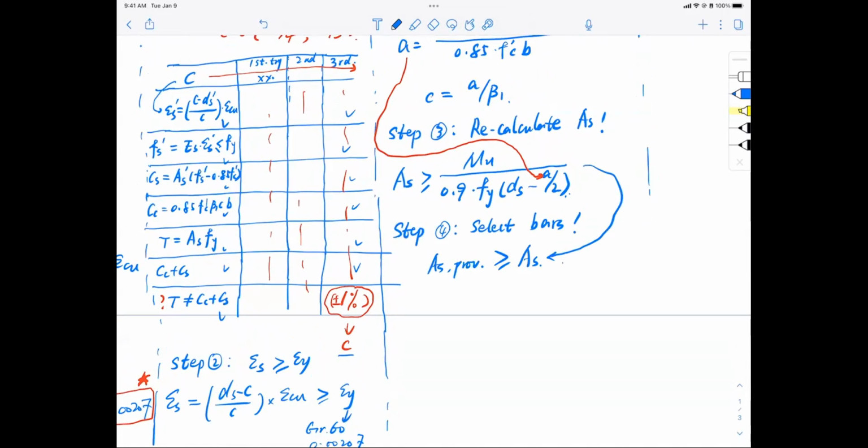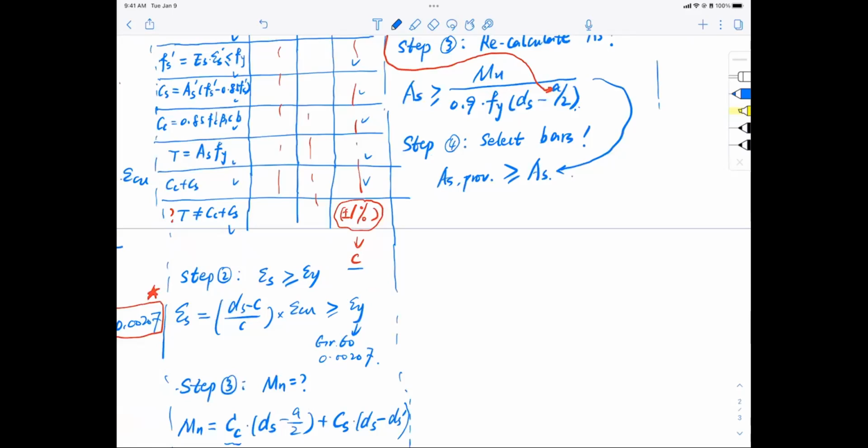At the end of step number 4, you have a width given by the problem, the height given by the problem, and the concrete cover, usually 2.5 inch or 3.5 inch depending on one layer or two layers. You now have As as well, say, maybe two number 9 bars. You select the bars, so you know everything.